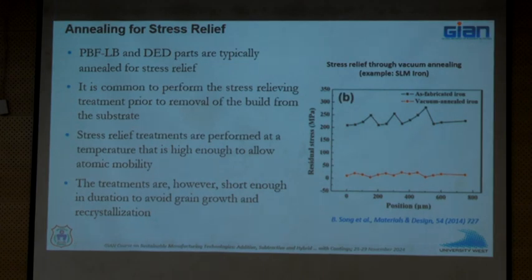Let's start off with what is often the most basic step for heat treatment, and this could be true irrespective of material many times. Imagine that you have a lot of residual stresses in your part, which is usually true in case of laser beam powder bed, also true to some extent in case of DED, and then it is very common to perform a stress relieving heat treatment at whatever condition is appropriate for that material, correct?